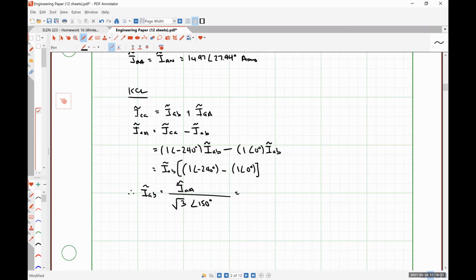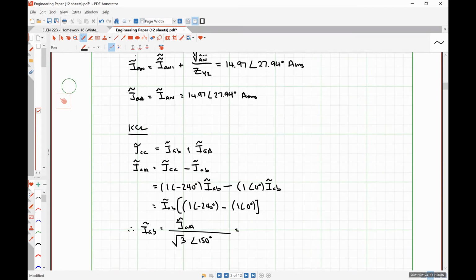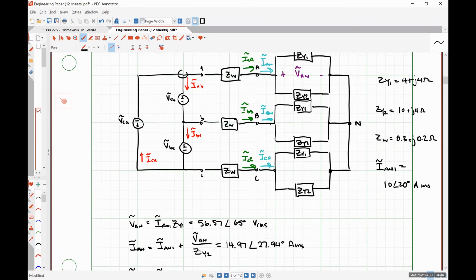Any questions, comments, concerns about that? Does that approach seem logical? Well, what I ended up doing, I found the wrong current. I found the delta current through the load, but there are no delta currents in the load because it's not delta connected. I don't know how I ended up finding what I found. Yeah. I mean, it was, would lowercase a equal capital IAN over 3?